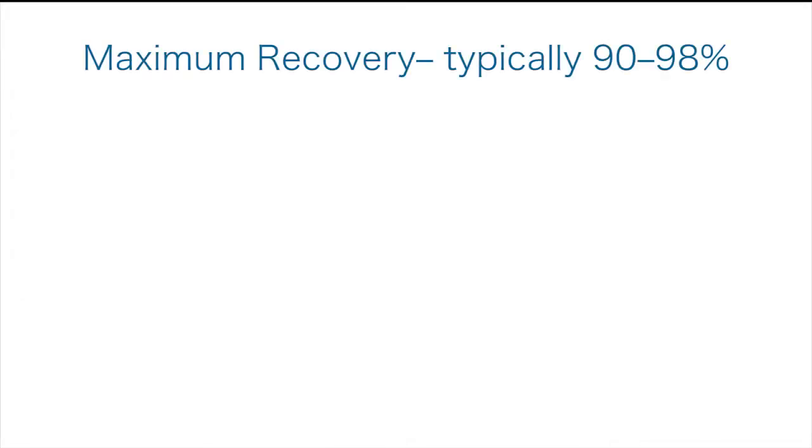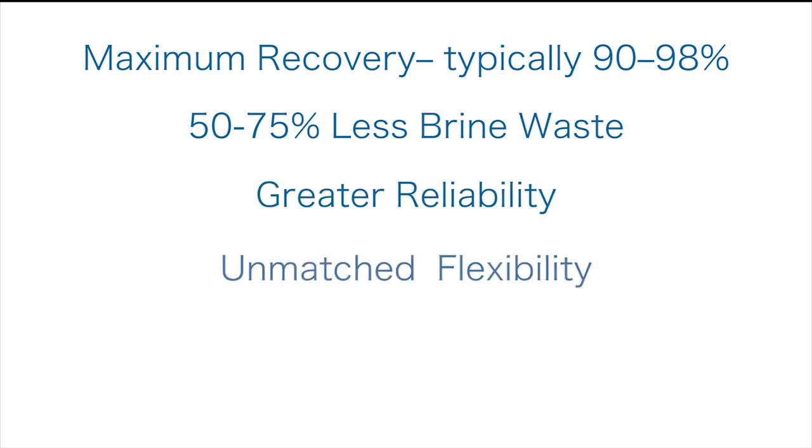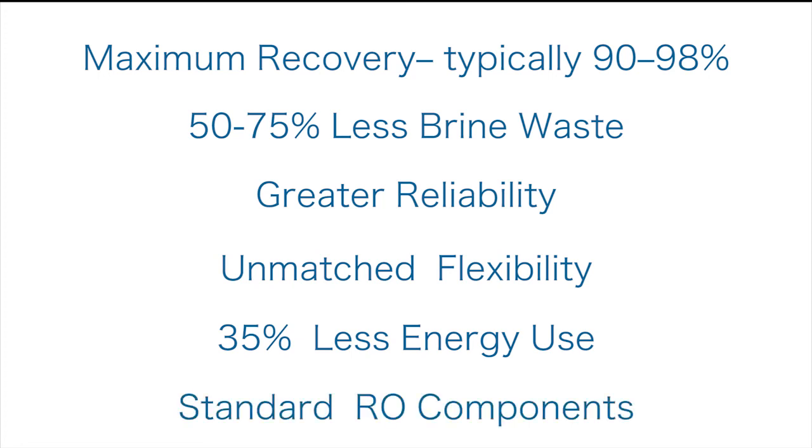CCD technology offers many benefits over traditional RO, including maximum recovery, typically 90 to 98%, 50 to 75% less brine waste, greater reliability, unmatched flexibility, 35% less energy use, and standard RO components.